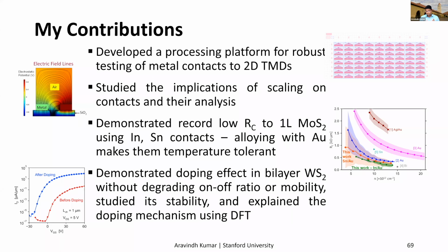Because I spent 2 years on a project trying to integrate III-V heterostructure contacts on MoS2, and it didn't work. So I could have spent that time on other ideas. By the way, do you know why that didn't work? What stopped it? The problem there was the processing issues. The III-V growth itself is damaging the 2D material because it has to be done in a hydrogen ambient at high temperatures. So we really couldn't find a way to integrate it without destroying the mobility of the channel.